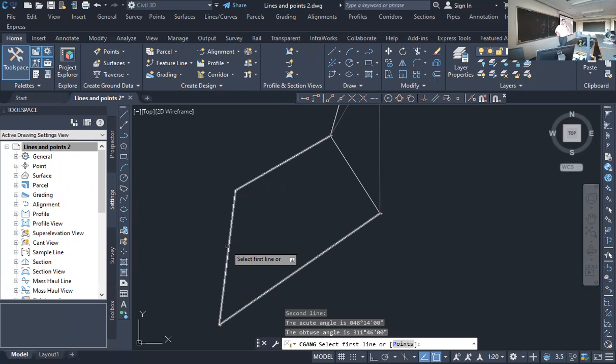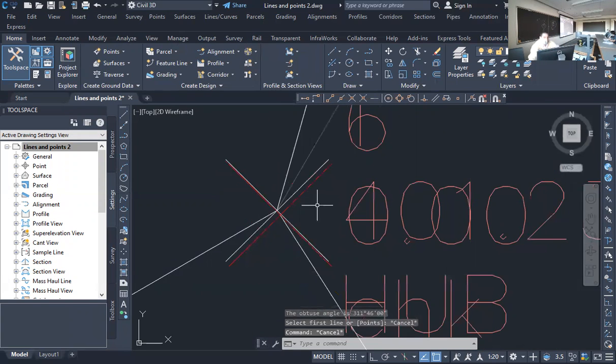Okay. Horizontal coordinates. If I started here and ended here, am I going to be smack dab right on top of that point? No, of course not. If your beginning coordinates and ending coordinates are exactly the same, I know you're fibbing. It closed. No, it didn't. Something went wrong and we dragged it. We're going to force it to fit. No. Show me how far it was off. How do you know how far you're off? Could you calculate the latitudes and departures? Of course you can. You know enough trigonometry. Can you do it in CAD?